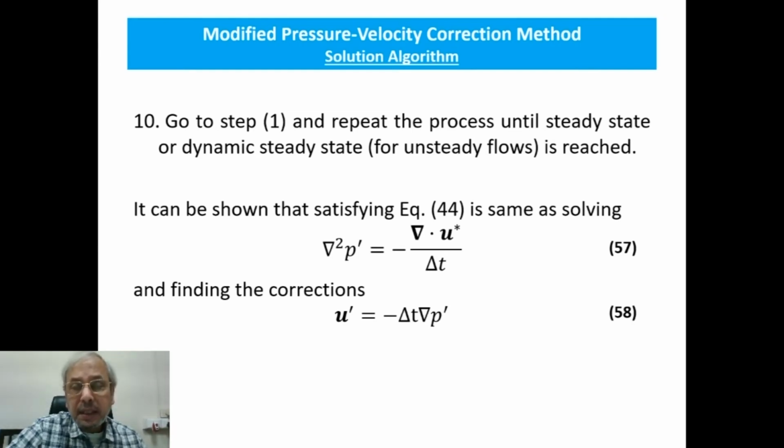As I said, zero means steady state, but in numerical computation getting zero is difficult, so it will be less than some predefined upper bound, maybe 10 to the power minus 3 or 10 to the power minus 4, and then we have reached the steady state.